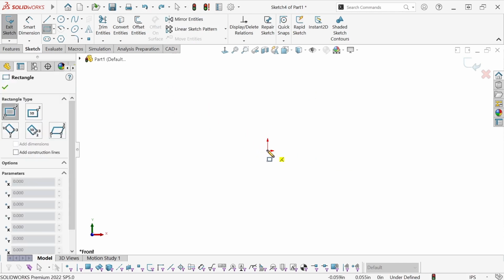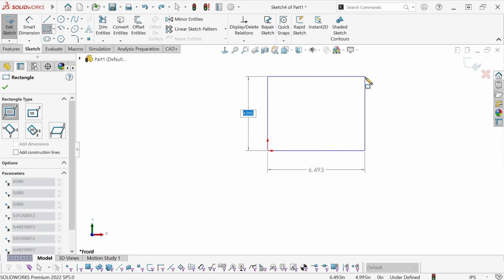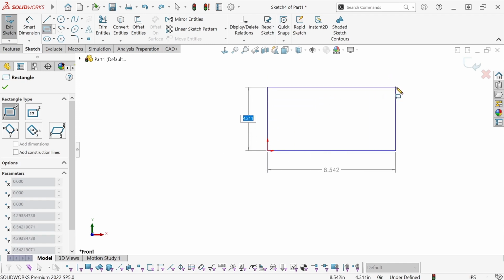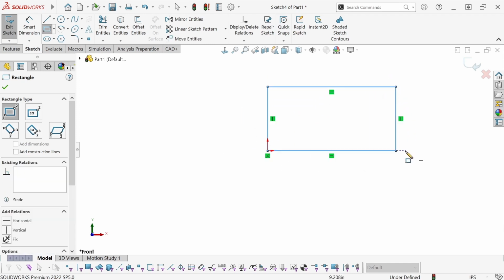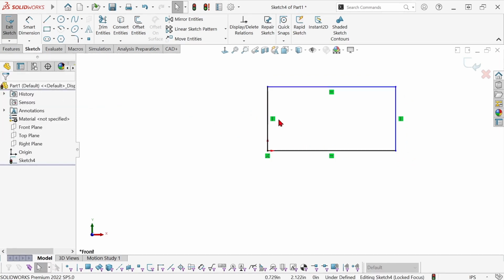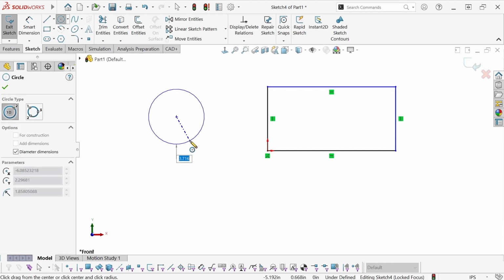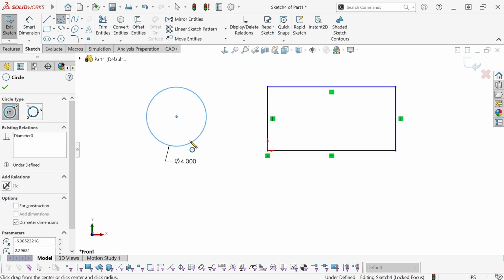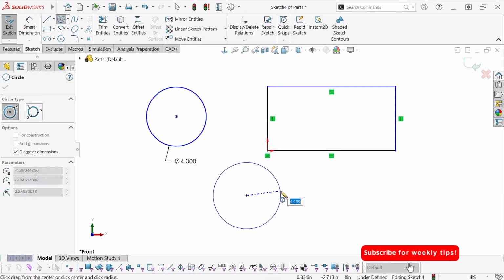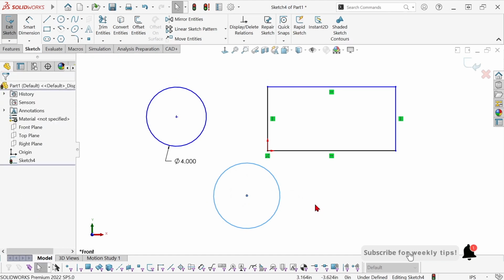So now, say I don't want to automatically size it. Well, I don't have to. I can just click to place the geometry, just like any time before, and the behavior is what we would consider normal. So when I do create an object and I want a dimension, I can type in a number, and if I don't want a dimension, then I just click. And this can really speed up your sketching. I really like this option, and I pretty much always leave it on.